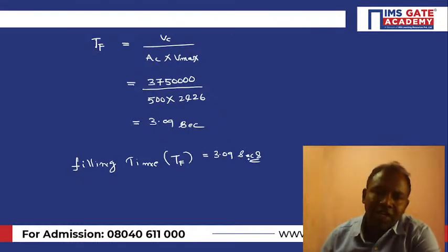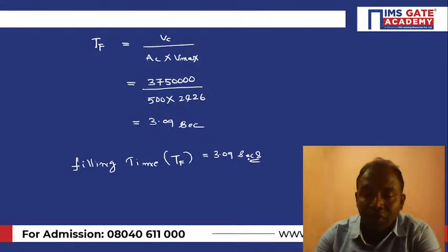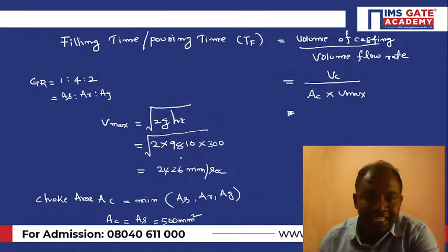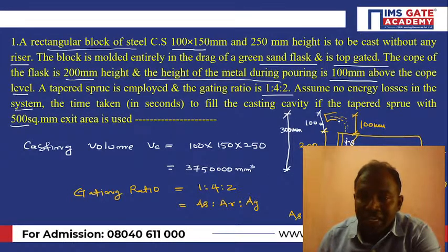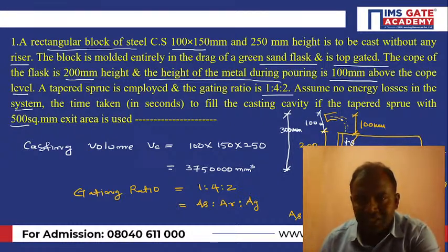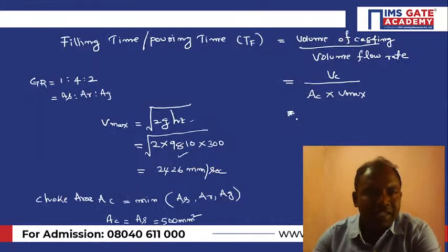All right guys, now here you have to be very careful while you are taking the Z, as well as while you are calculating the T also. Now from where the molten metal is pouring, from there you have to calculate the T. So here the molten metal is pouring from here. Okay, so that is the reason why. So here I'll write the diagram again.